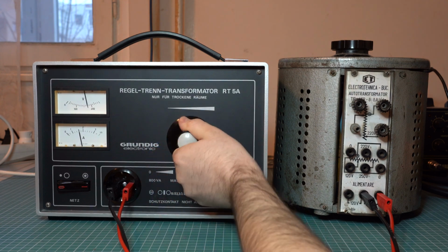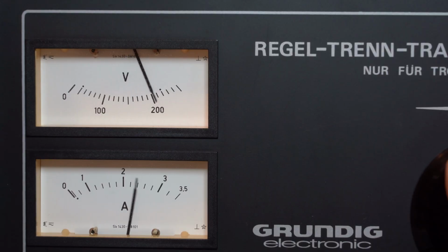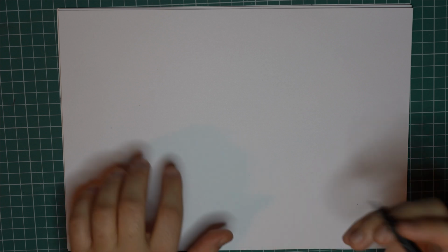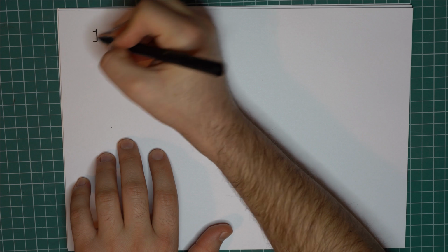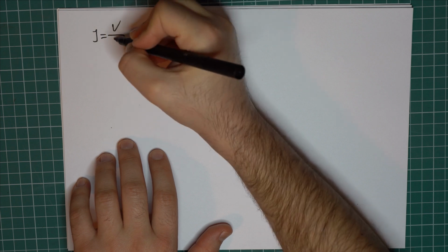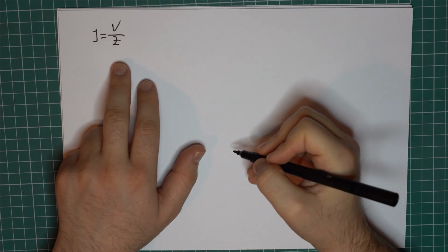So far so good. And at 220 volts we have a current of around 3 amps, so it is much lower than the 230 amps that we calculated earlier. So to analyze what happened in our experiment, we have to talk about some concepts. First of all, let's talk about Ohm's law in AC circuits. Well, in AC circuits, Ohm's law applies a little bit differently. So I equals V over Z, where Z is the impedance.